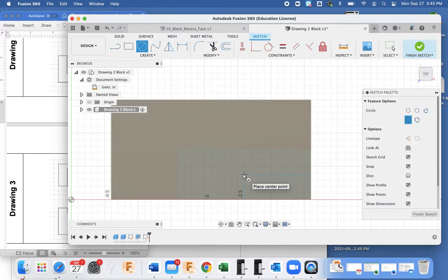Okay? Those are called witness lines. So if I grab the center point of one, see, come along, find that center, and it snaps and pull it up, it will find any other witness line that I've already been using. And I'd already used that one from over here. So it automatically jumped together. And I could put that there. And then I pull out my circle and I can tell it however big I want it to be. I want it to be 0.5 diameter.